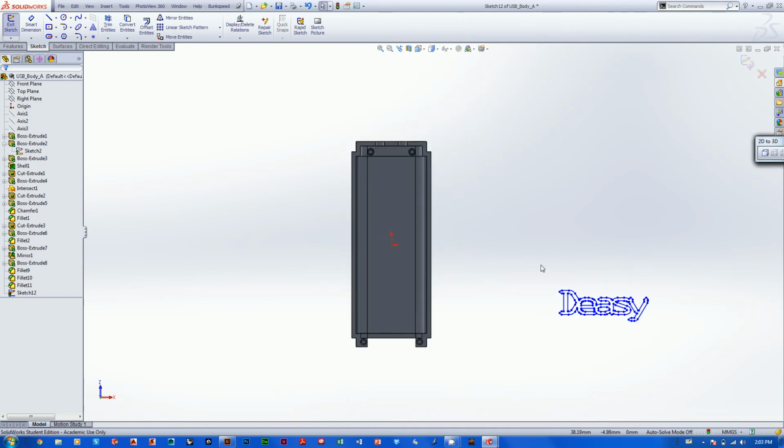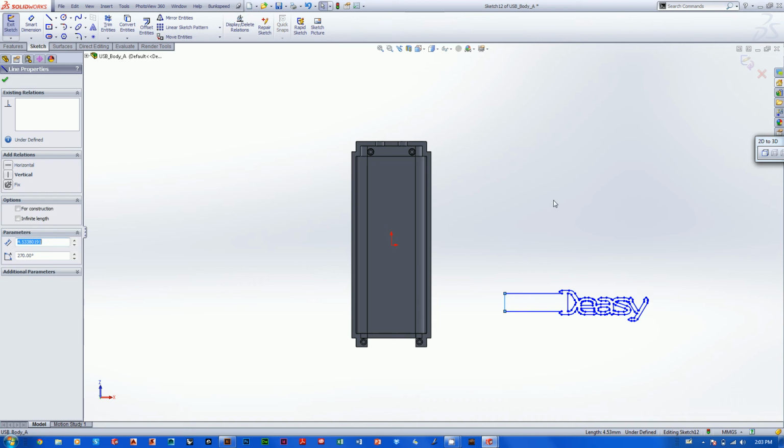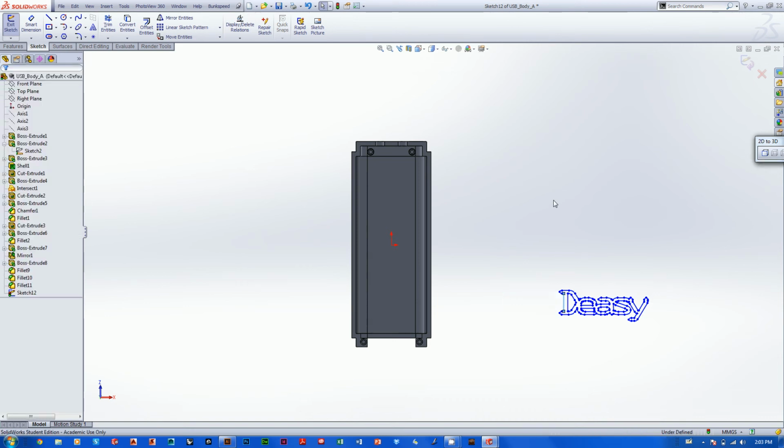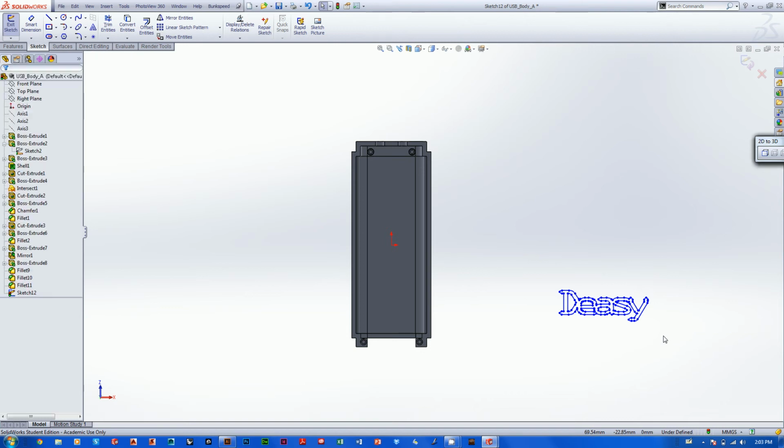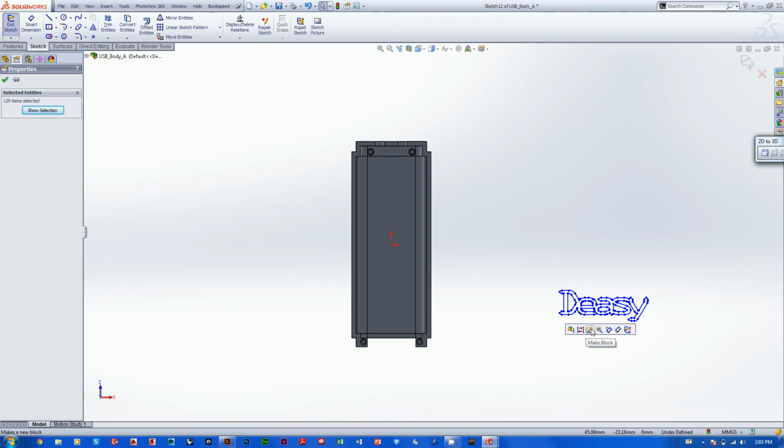So now this has shown up as straight up line work, okay? And we want to be able to move it, right? If we try to move it, it moves around like that. We don't want that to happen, all right? So what we want to do is flatten all of this line work together, okay? And the way to do that is with a function called make block, all right? So I'm just going to draw a box around the entire logo and go here to make block.